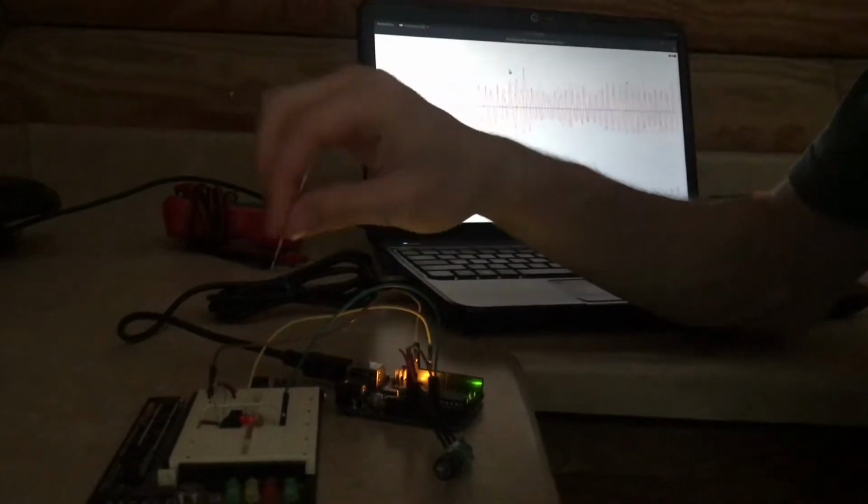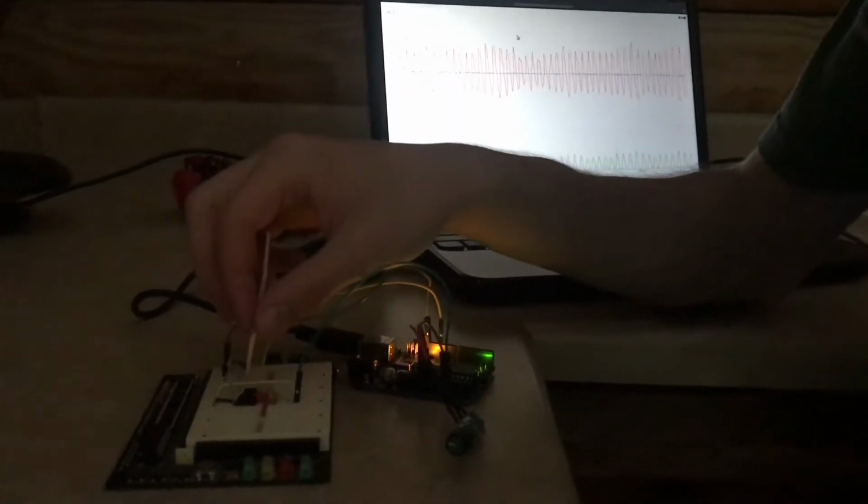So as a very basic stripped down example, I have a little LED shining at a light dependent resistor, which is a type of light sensor. The more light striking the sensor, the higher the voltage produced on the sensor. And you can see whenever I put a piece of paper between the two, the LED will increase brightness in order to make sure that the same amount of light strikes the sensor.